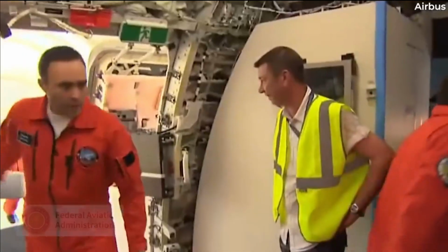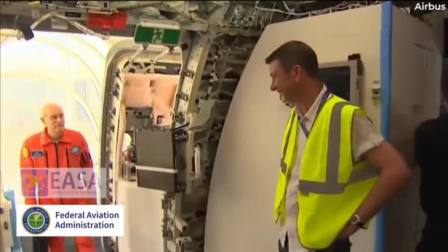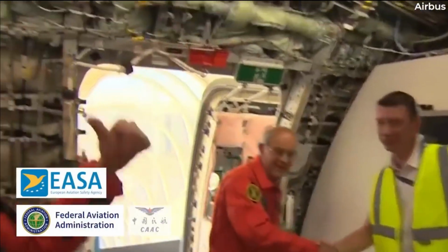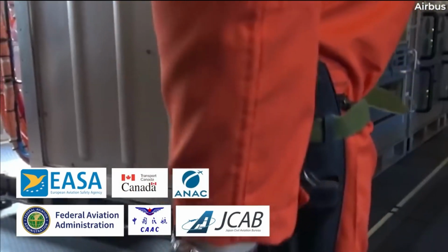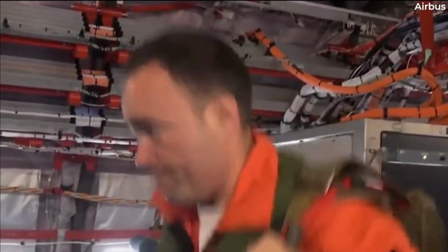If an aircraft is flying with a Special Airworthiness Experimental Certificate, FAA Form 8130-7, Special Airworthiness Certificate, Pink Color Certificate, and that is the only airworthiness certificate this aircraft has ever had, then 14 CFR Part 43 does not apply.